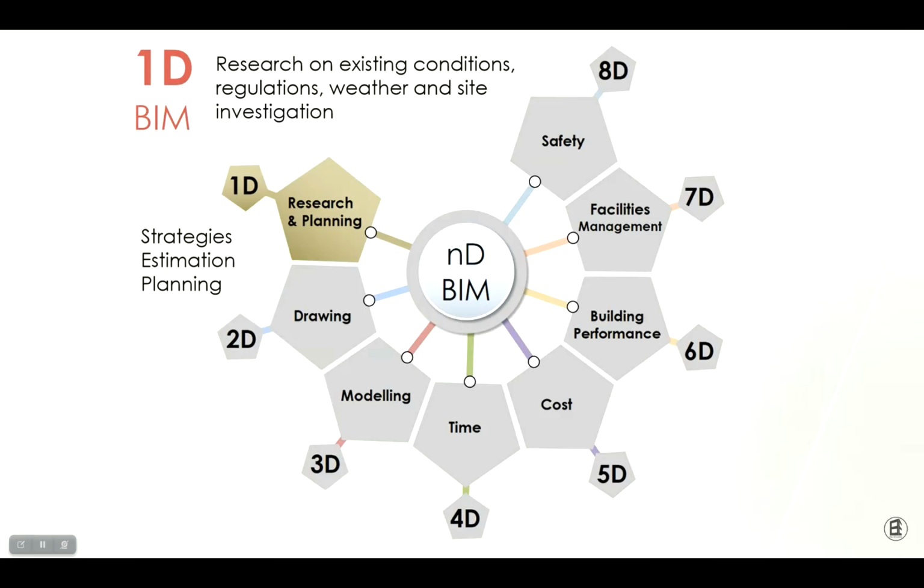Weather conditions and site. Weather is going to be different at different places. When we talk about structures, we talk about wind analysis or earthquake designs. We talk about the zones. If I am in Delhi, the wind is going to be about 47 meters per second.